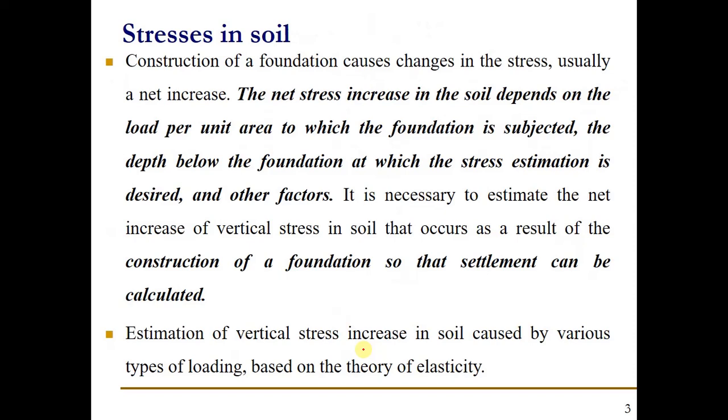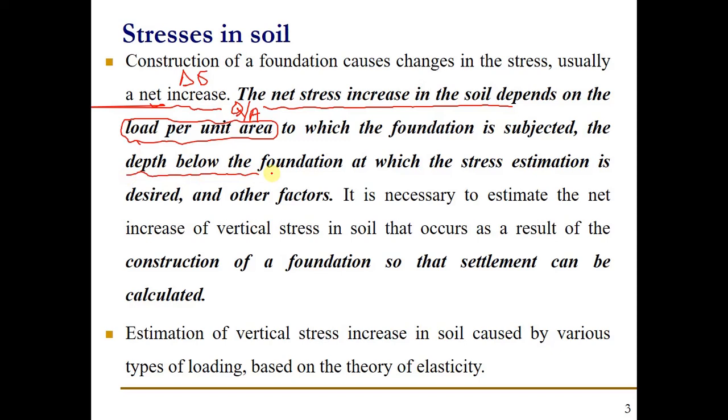Now, construction of a foundation causes changes in the stress, usually the net increase. We can call that delta sigma. The net stress increase in the soil depends on the load per unit area, Q by A, to which the foundation is subjected, the depth of the foundation at which the stress estimation is desired, and several other factors which will be discussed in the foundation engineering as well.